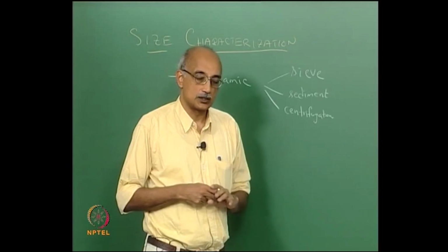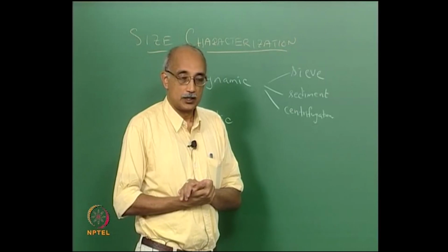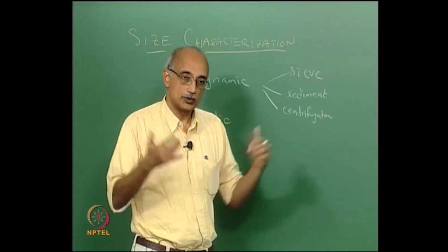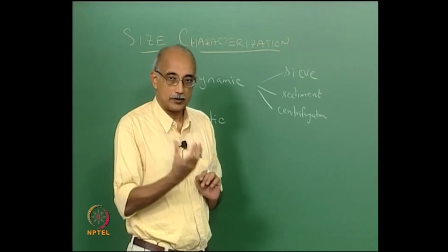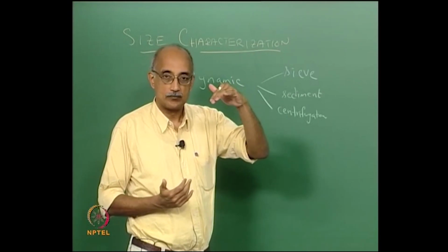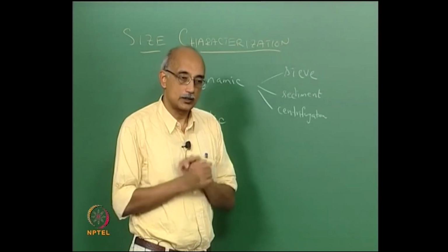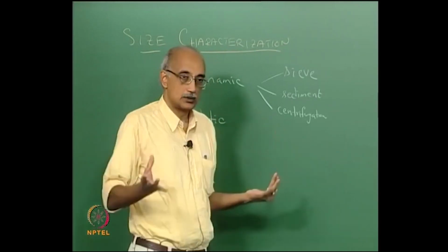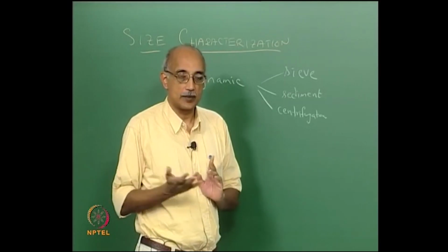How about centrifugation? I am sure you have done air classification type of experiments where you take a population of particles, introduce it into a chamber, and then you introduce flow of air so that the particles introduced, for example, from the top may get entrained in air that is blown from the bottom, and particles of different sizes and different masses will be blown to various radii of this chamber depending on their size and mass characteristics.